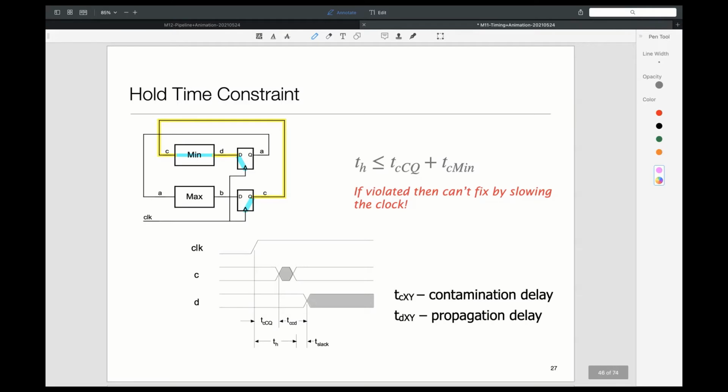Okay. What exactly happens if this is violated? Great question. At that stage, you cannot guarantee that the flip-flop is getting the correct value. And it's not simply that instead of 1, it may be a 0, or instead of a 0, it may be a 1. It may actually get into something called metastability failure.